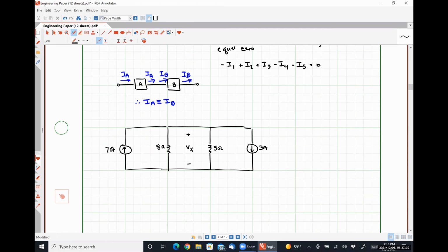So I'm going to apply Kirchhoff's current law to this circuit. So you guys tell me, we apply Kirchhoff's current law at a node. Should we use the top node or the bottom node? Top, okay. Should we use formulation 1, 2, or 3? 3, okay. So I'm going to apply KCL at the top node. And I'm going to say currents leaving positive. Because that's what formulation number 3 does, treats the leaving currents as positive, okay?